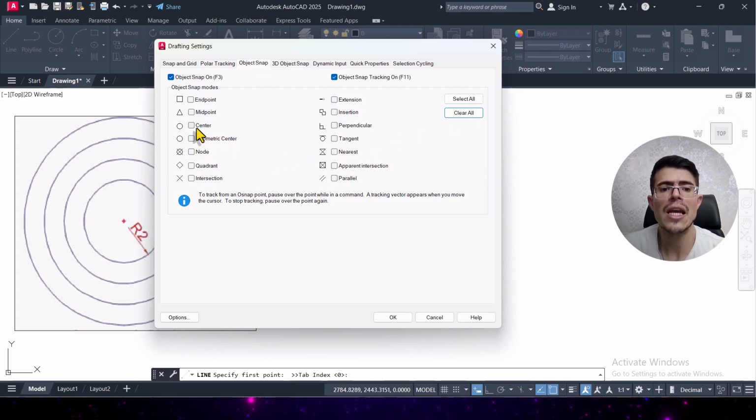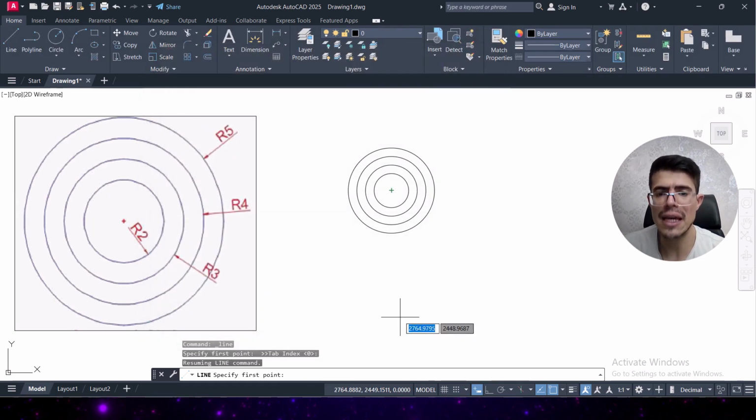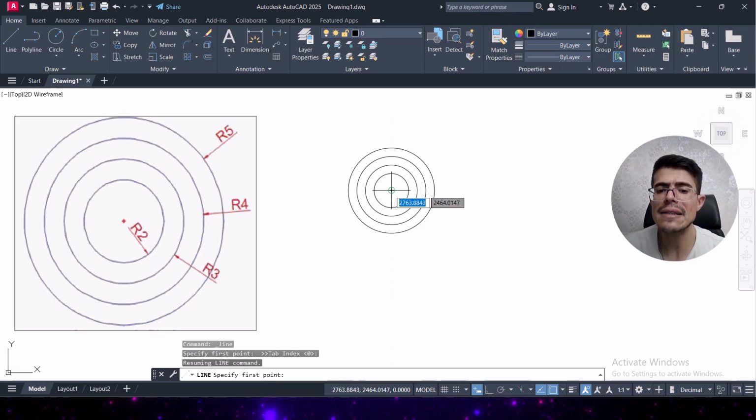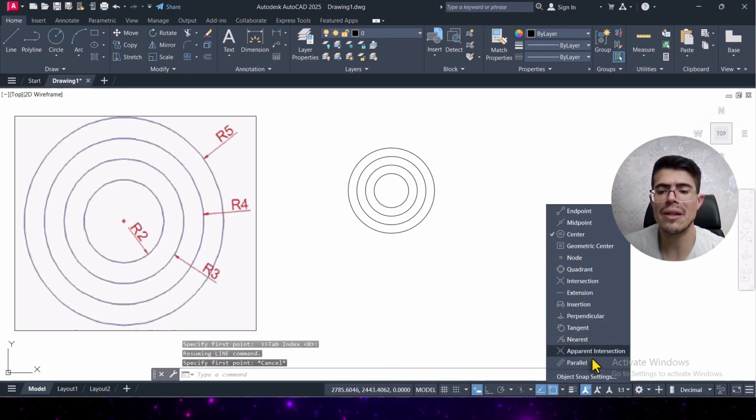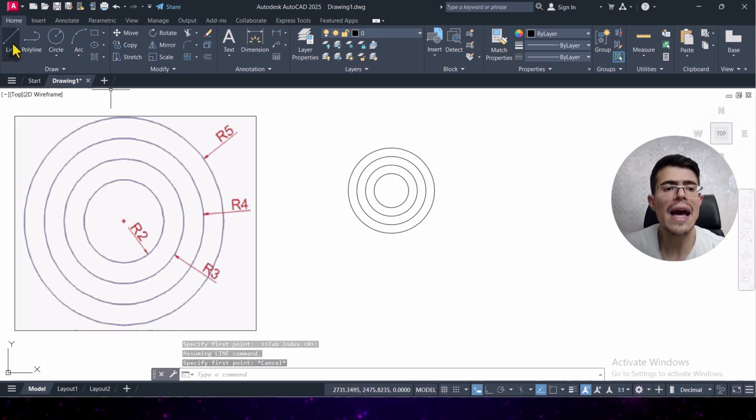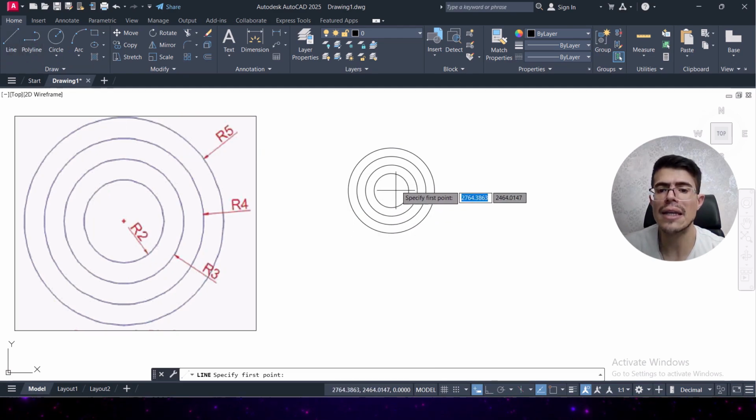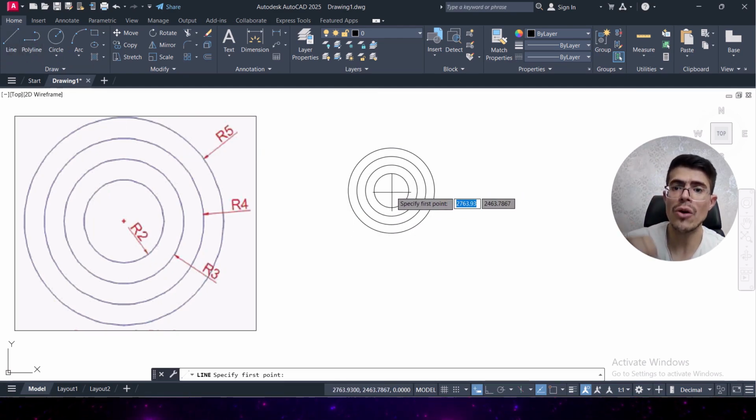Let's come to this part. If you use the center, you see the circle point. And I say OK. I can access this again, a gray color with a circle point which shows the object snap of the center. Now it shows the center of this circle. If I turn it off, and for example want to select this center, I cannot do this. So it was the point of using object snaps to make our drawings faster and also more exact.